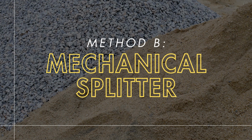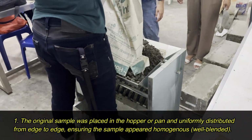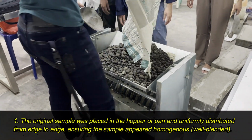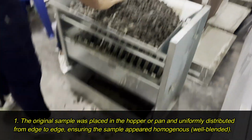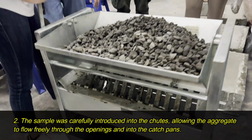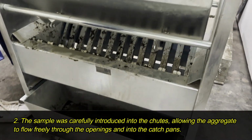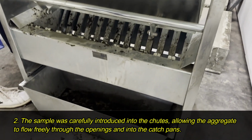The second method in this test was a mechanical splitter. In this method, the equipment used was a mechanical splitter. First, the original sample was placed in the hopper or pan and uniformly distributed from edge to edge, ensuring the sample appeared homogeneous, well blended. Second, the sample was carefully introduced into the chutes, allowing the aggregate to flow freely through the openings and into the catch pans.